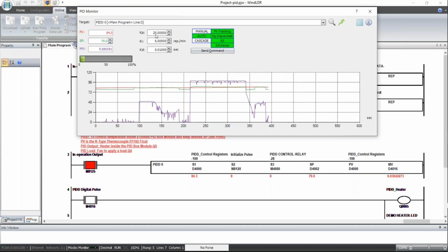This is where I always recommend your gain be about 2 to 3, 2.5 to 3 or something. Because whatever goes high, look how fast it dropped here, right, versus here. You want a gradual change. So let me go back to 85 and let it sit there and see how it adjusts.